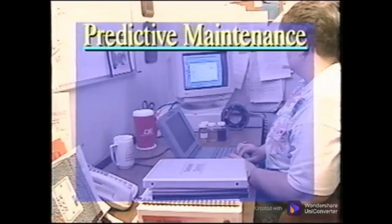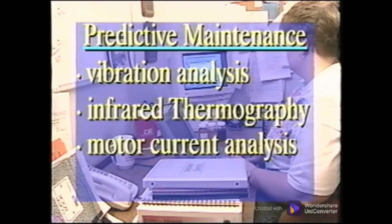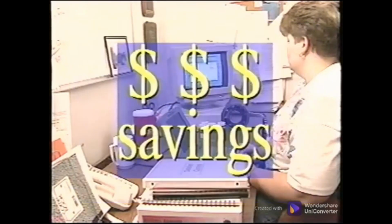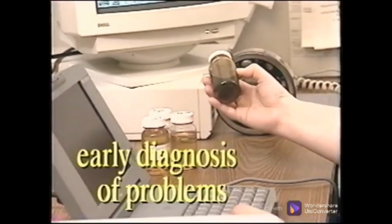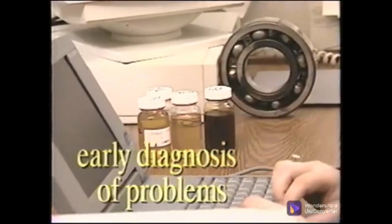This predictive maintenance philosophy is actually much more involved than condition monitoring and uses many technologies such as vibration analysis, infrared thermography, motor current analysis, and oil analysis to determine the present condition and predict the future for the machine. Predictive maintenance programs have proven savings of millions of dollars in maintenance costs. Oil analysis in a predictive maintenance philosophy capitalizes on the program with early diagnosis of problems, which in some applications go undetected with vibration analysis.